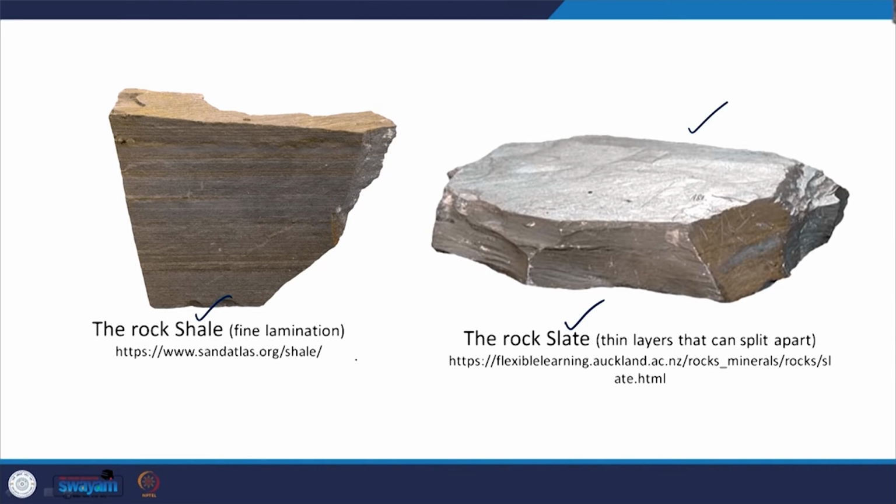They are foliated, as you can see here in these two pictures, very fine grained, hard and brittle. Color can be variable: black, shades of blue, green, red, brown and buff can be found. Usually they contain mica minerals, which typically impart a sheen on foliation surfaces. It is smooth to touch for both these rocks.